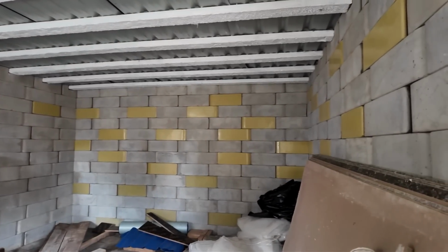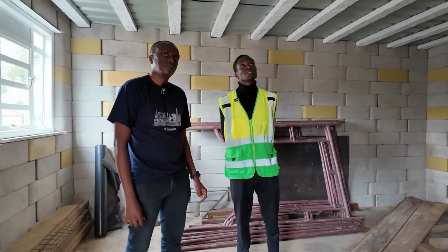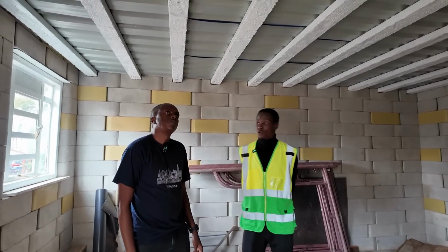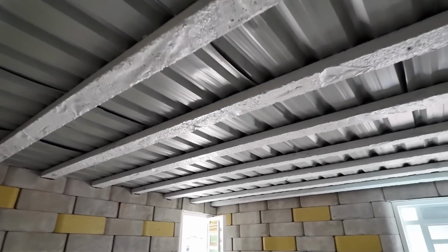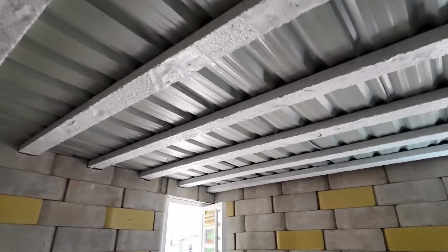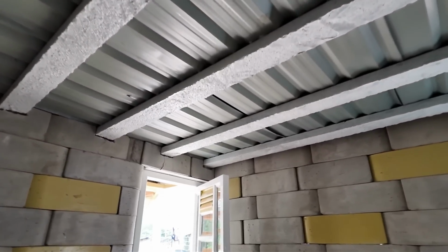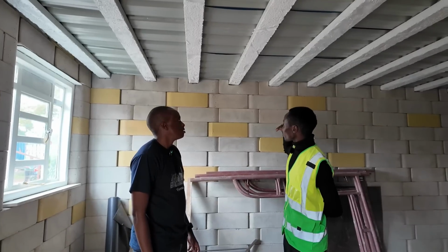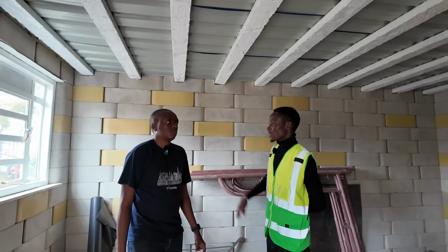And how we've done our roofing from above, if you can see it from that end, we've been able to utilize T-beams. These are T-beams. We get them from Eco Concrete, and the beams are the ones which have held the first floor slab intact. So they transfer the loads to the beam of the twist blocks round. That is where you see the blocks have been cut. That is the ring beam course. So that is the only course that is concreted in this whole structure. The T-beams rest on top of the beam that is casted, and you're able to distribute the load properly to the entire structure.